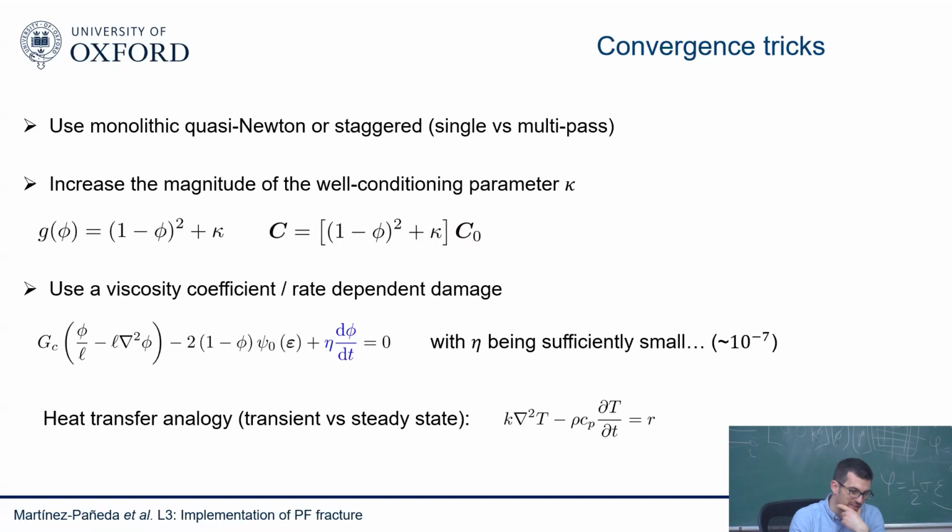For example, if you imagine, I don't know, a large strain elastoplastic problem, if your elements have no load carrying capacity, they're going to be extremely distorted because they're going to deform all over the place. So retaining a little bit of load carrying capacity is good. And initially, I started using 1 to the minus 7 with this one. And I found out that it was good.